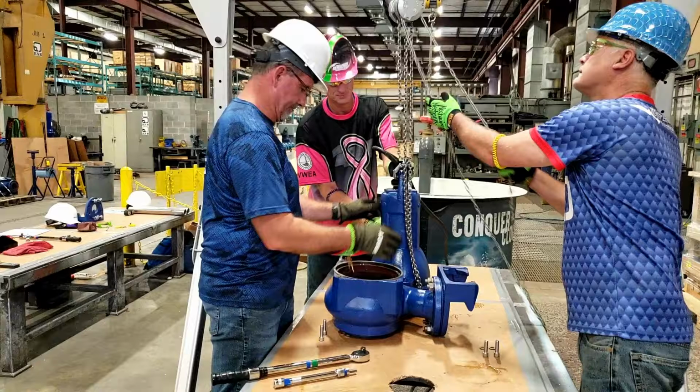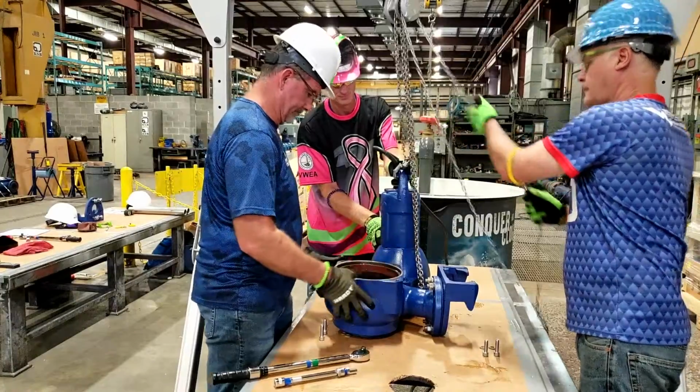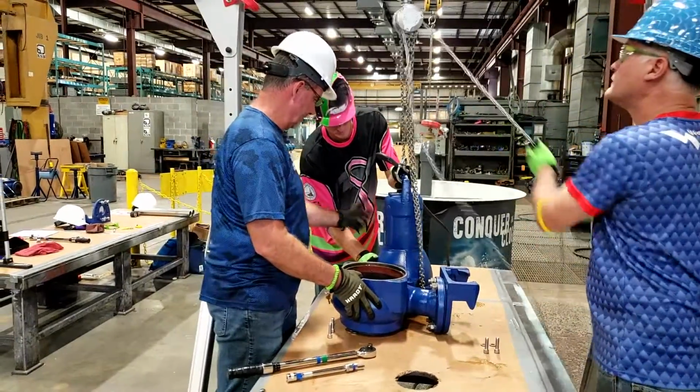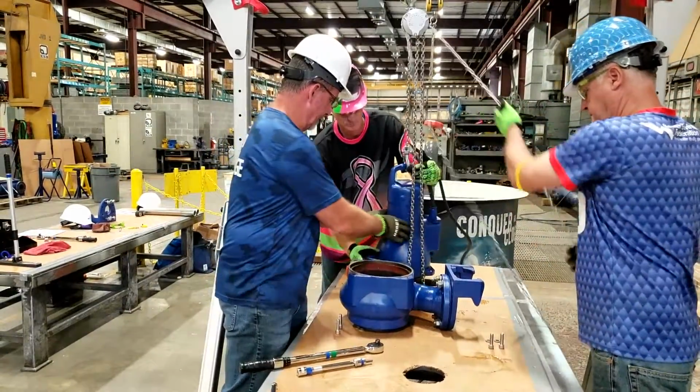Note, when placing the pump back in the volute, the orientation of the pump shall be such that the electric cord connection is on the opposite side of the guide claw and pump discharge. Using the gantry and chain hoist, lift the pump back into the volute housing.